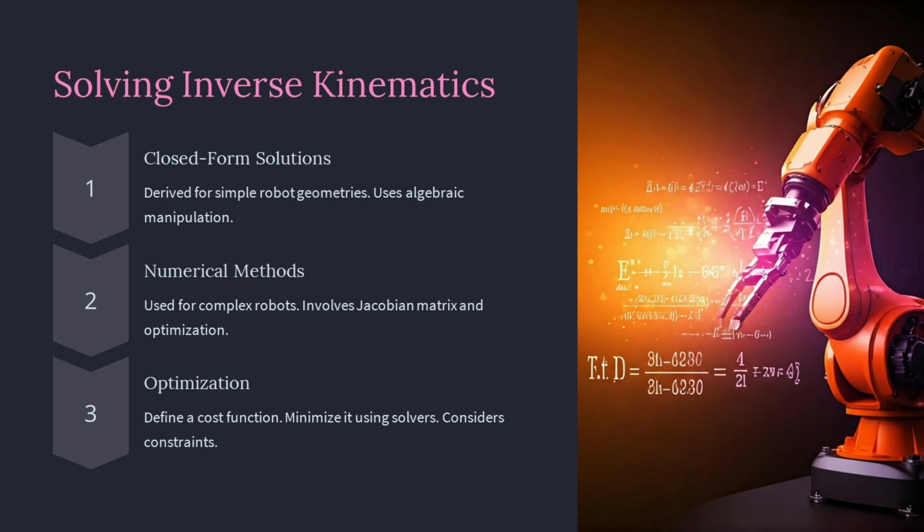then the Jacobian matrix times dot theta equals that spatial velocity. To solve inverse kinematics, we compute the difference between the current end effector pose and the desired pose, which we call the pose error. We then multiply the pseudo-inverse of the Jacobian by that pose error to obtain a set of joint velocity commands. By integrating those commands over time, the joint angles converge gradually to a configuration that reduces the pose error to 0 or near 0.